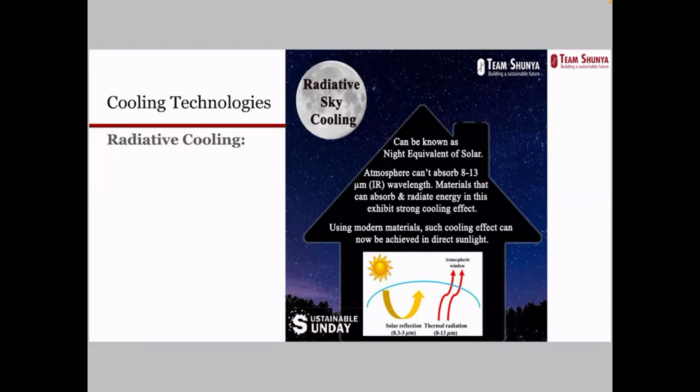In that particular case, instead of receiving the radiative energy, they emit low temperature, long wavelength emissions from the panel itself, and due to that emission the temperature keeps on dropping, and that technology is easily adaptable in climates where there is a clean sky. So that kind of technologies are in development, are more energy efficient and can be adopted in the house to reduce the cooling requirements.